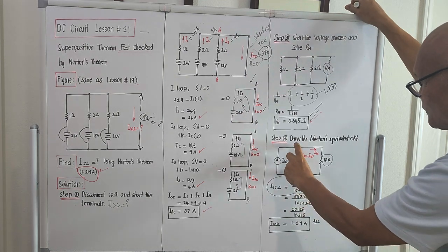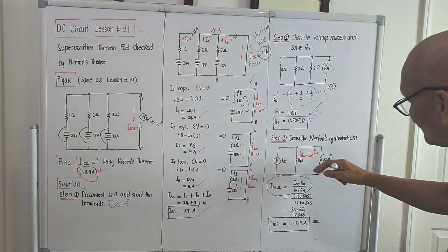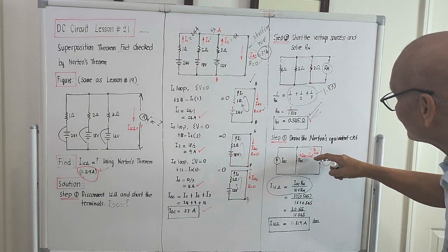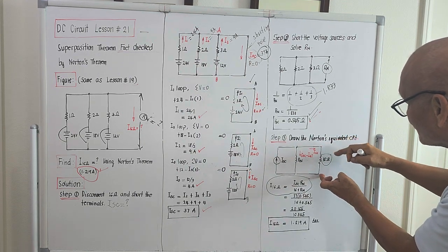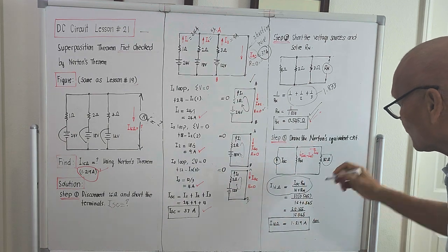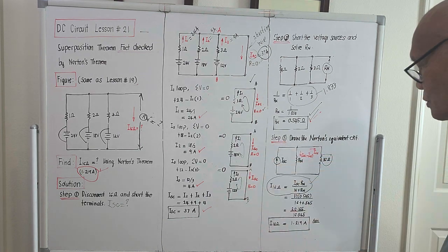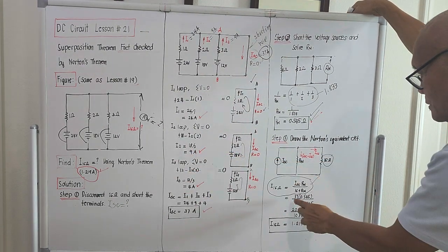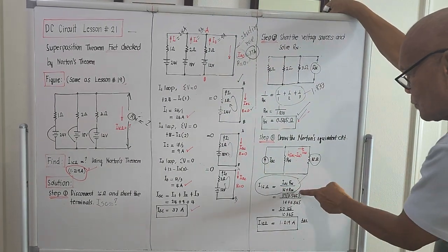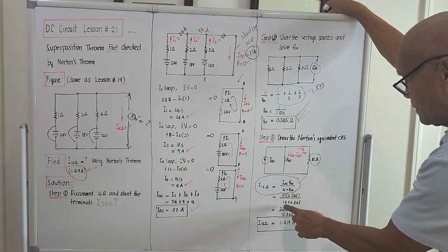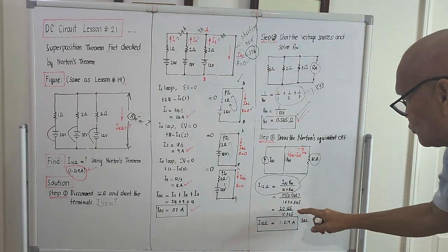If we try to take the product of the current passing here, and the voltage across this one is same as this one, so if we try to take the product of short circuit minus I sub 16 times this, and this should be equal to the voltage drop across this, it will be I sub 16 times 16. And if we try to simplify, this will be the equation. Okay, so it's just a matter of direct substitution now. The short circuit current is 37. The Norton's resistance is 0.545 all over RL, which is 16, plus the Norton's resistance. So this will be 20.165.